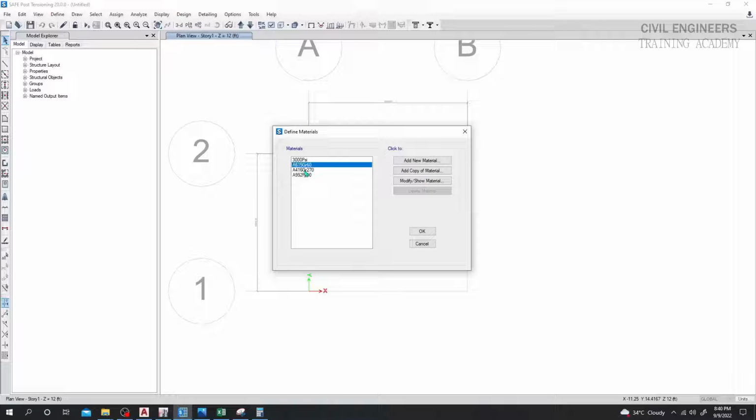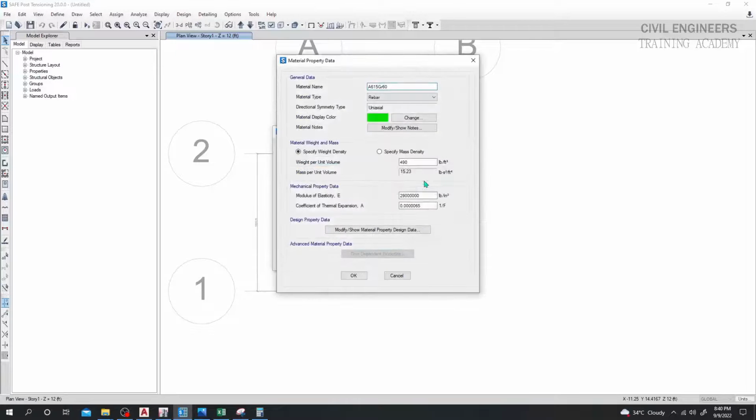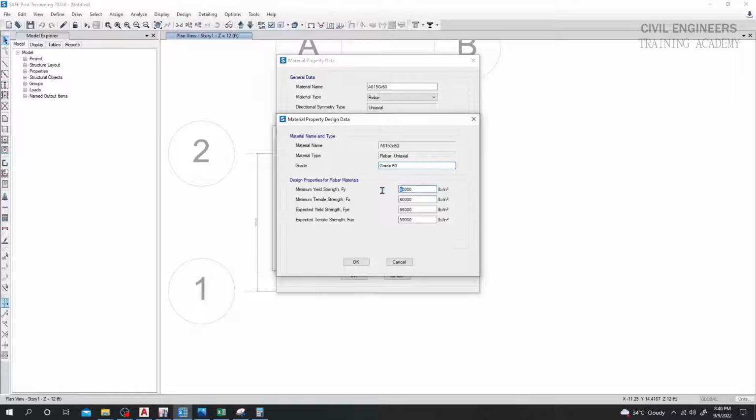And we'll change also for our grade steel. Everything will be okay here, and the only change here will be 72500. Actually, as per your requirement, you will provide that value, then copy that. I'll copy that value, and this value will be 1.25 into fy. It's done.